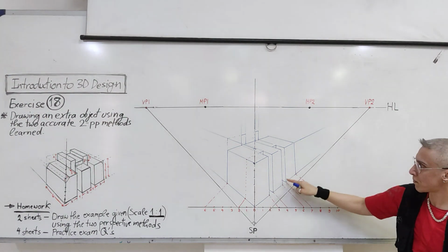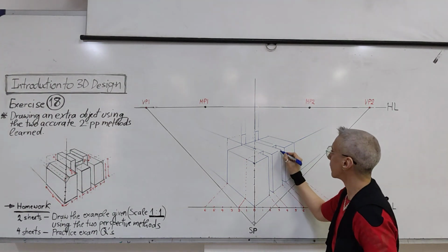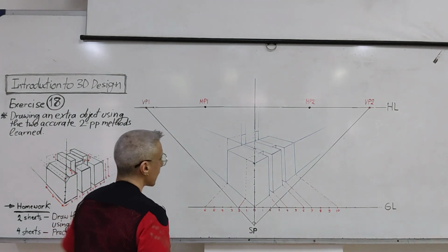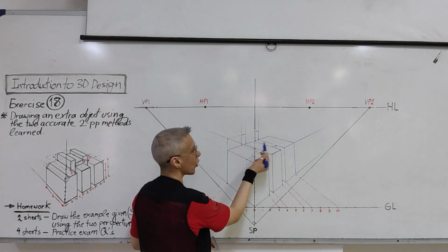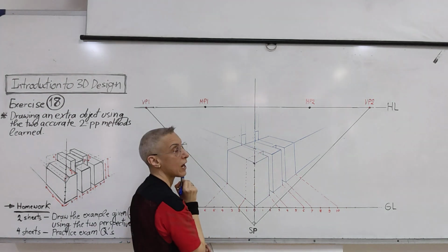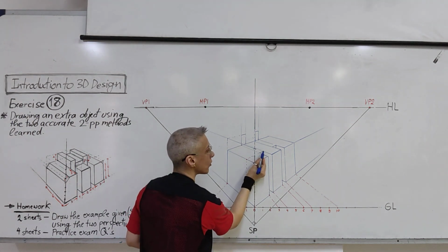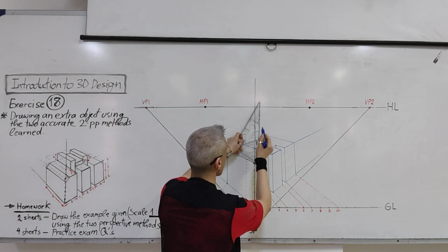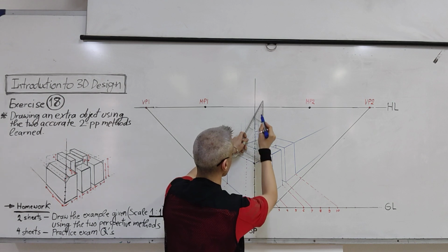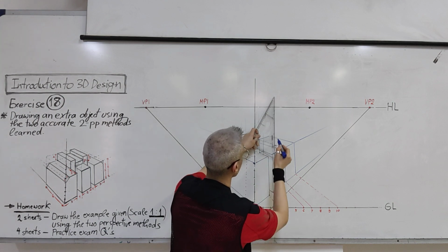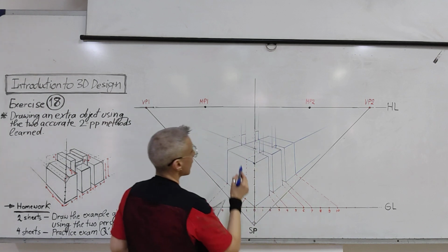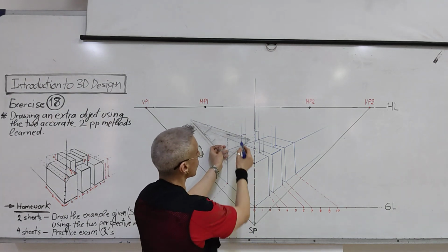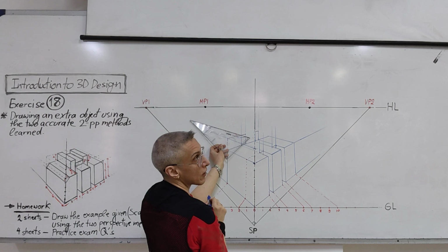So this here is an opening, and this here is an opening. Now, this object will go up. We already found their height, and we already found where this point is, this and this. So let us extend lines up from here, from here. Since we found this point already, and this point, and this, and this, we will take to the vanishing point, going through this point, and see where it will intersect here.